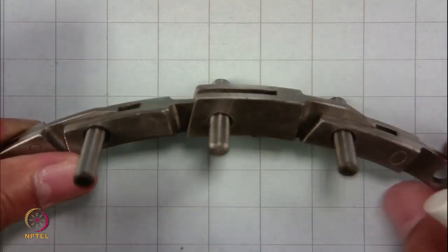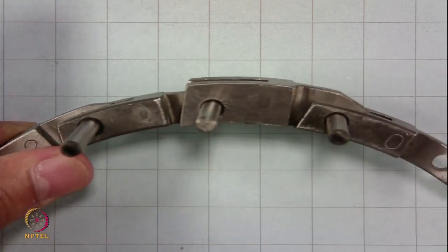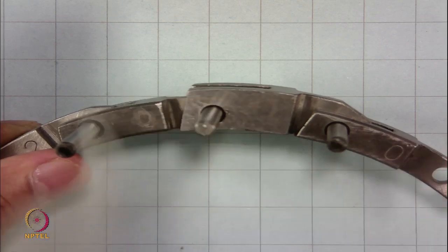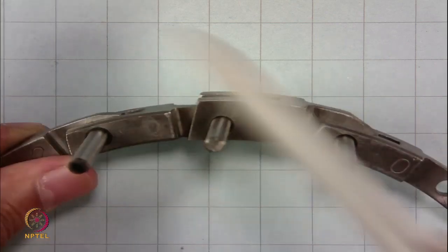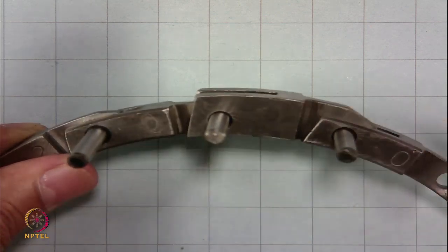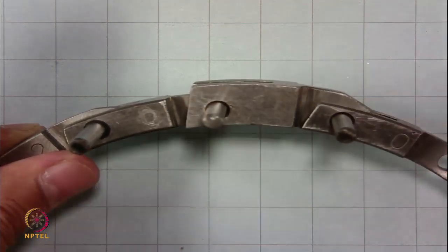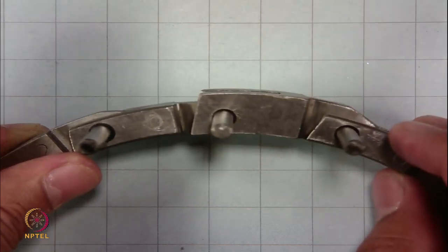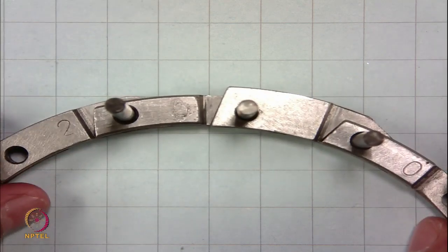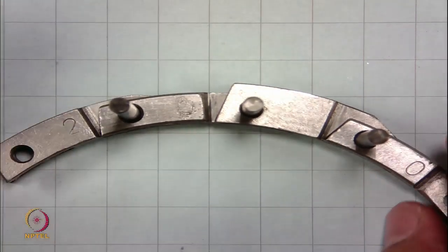So, in this way the sequences are designed and you are achieving overlap and underlap of different amounts. Usually whenever overlap is happening it is equal to one pitch. Whatever depression you are looking at, the distance of this depression is equivalent to one pitch, and if you are looking at this point here, the depression is much more, it means you are doing more than one pitch of underlap. So, underlap can have more than one or two pitches, but overlap is usually one pitch or 0 pitch.